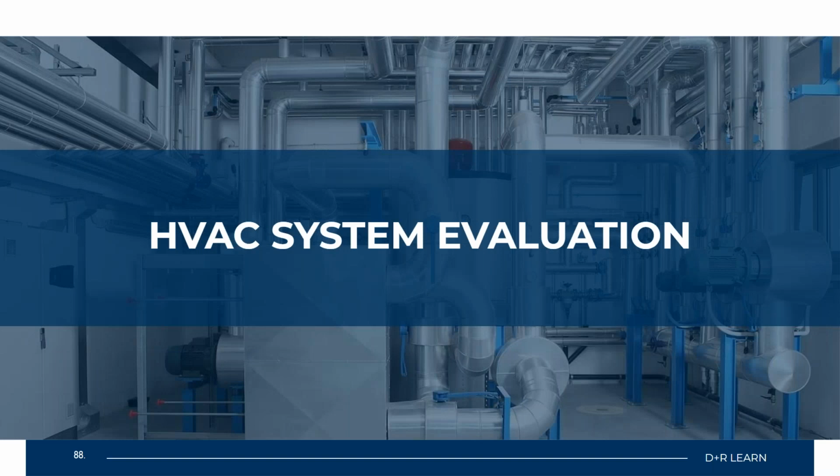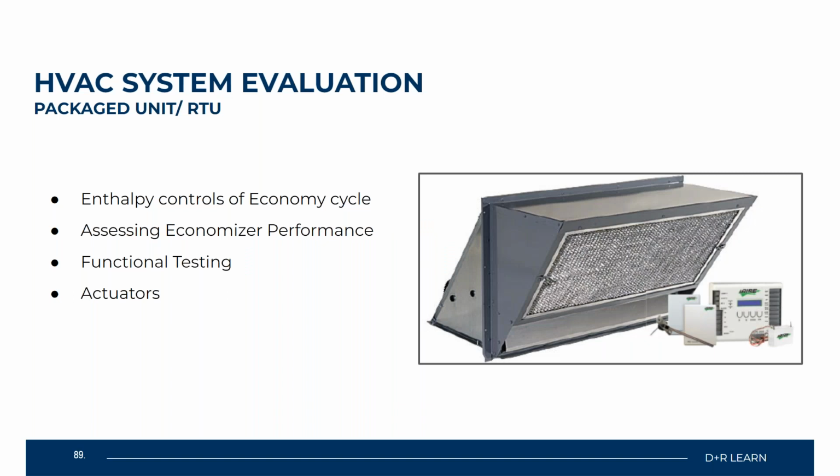So, HVAC system evaluation. Now we're just going to take a really quick look into how we're going to evaluate these systems. With your package unit RTUs, we're going to take a look at enthalpy controls of your economy cycle. And this is just where you're bringing in fresh outside air into your system. You want to make sure that those controls are operating and able to bring in 100% outdoor air when the system is calling for it.